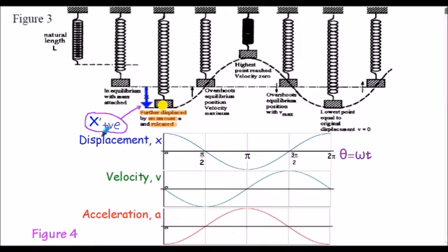Notice the positive direction for x is downwards. So on our diagram we have a positive x displacement. We will have no velocity because at this point the mass is stationary. But on release of the mass we will generate an acceleration due to the stiffness of the spring and the extension of the spring.